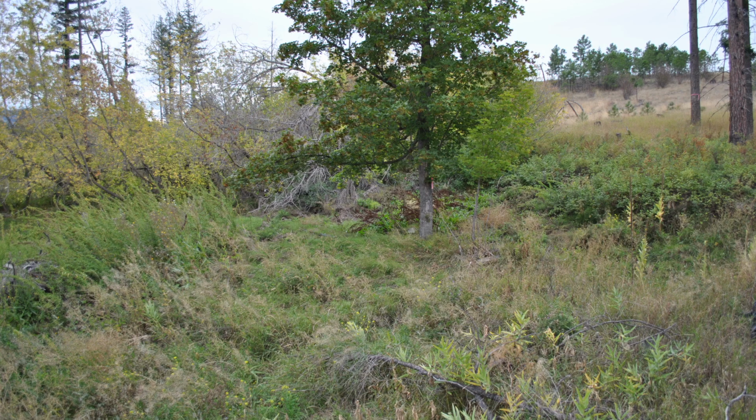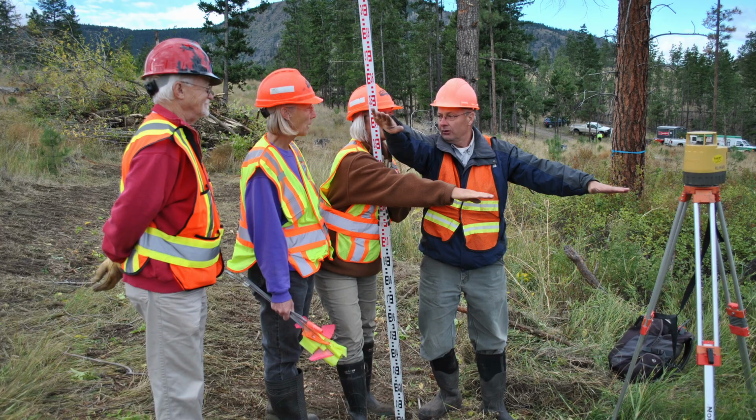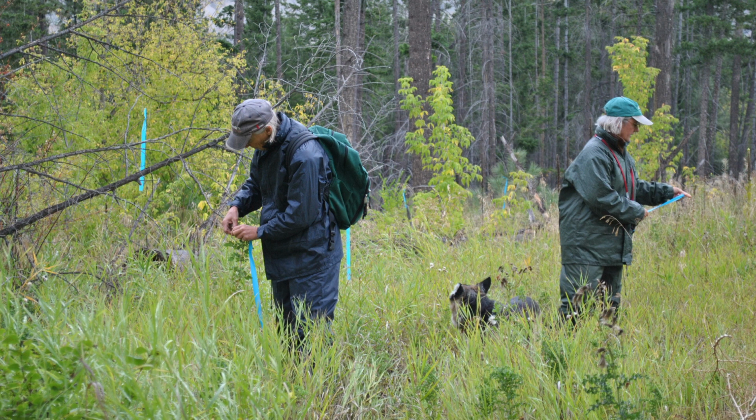We designed wetlands to be built on a mountainside where water from springs had saturated the soil. The use of the laser level showed us that the ground was steep, with slopes varying from 6 to 9%. We designed the wetlands to stair-step down the slope. Each area we marked in the ground would have from a 3 to a 4-foot change in elevation from upper to lower edge. We marked the perimeter of each wetland we wanted to build with colored plastic flagging.